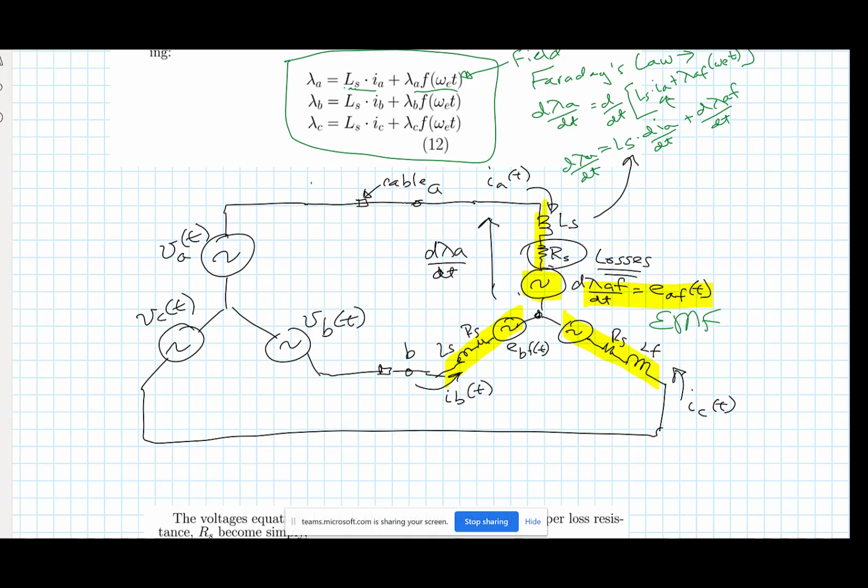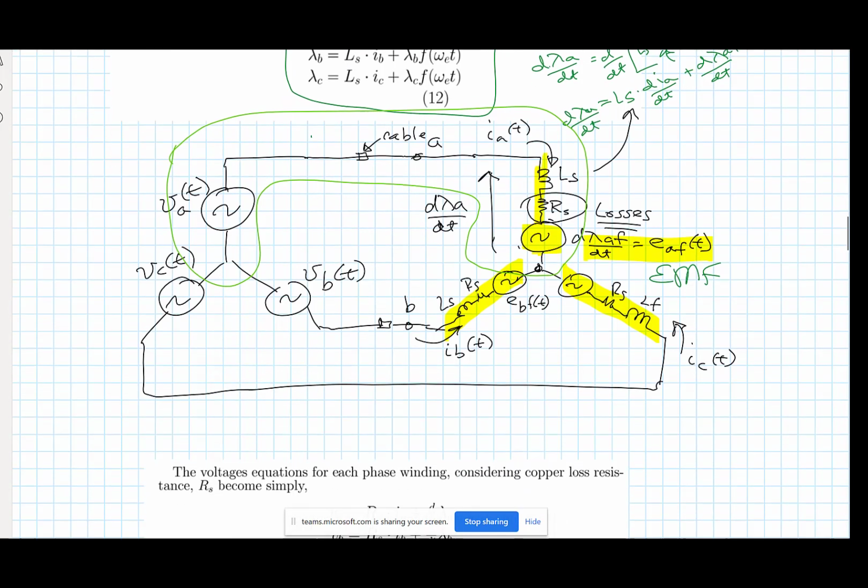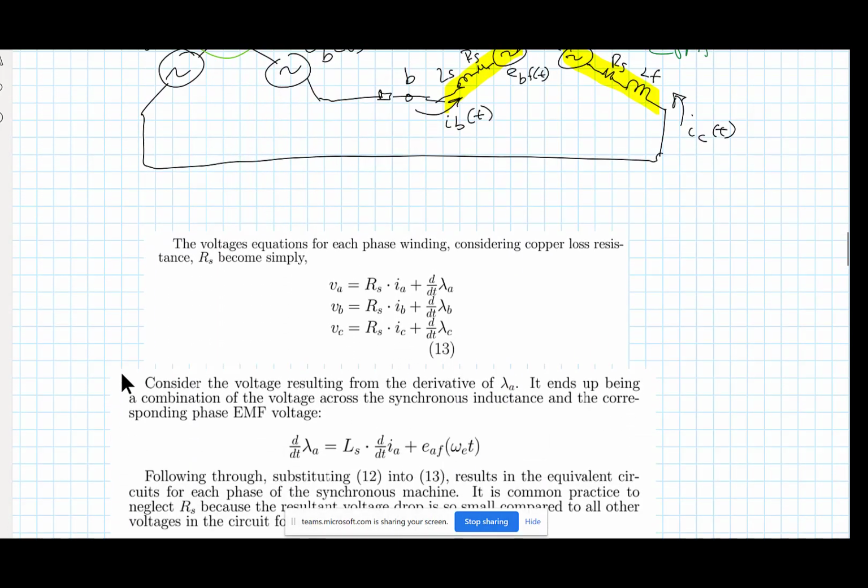So it would follow that I could analyze, just like we did with the three-phase circuits, the transformer, I only need to analyze one phase of this and multiply my result by 3, and I can get my answer, if I can get this into phasor form. So are there any questions on this? Does that make sense? Usually somebody says at least yes. Okay, I see one person said yes. Okay.